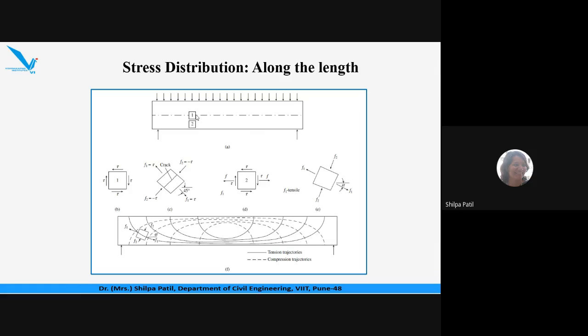So according to that, at the neutral axis, the bending stresses are 0, whereas the shear stresses are maximum. So if I want to show the stresses acting on this element number 1, it is subjected to pure shear because the bending stresses are 0 at the neutral axis and shear stresses are maximum. So along with this particular element 1, if I draw a free body diagram of this element, I can show here the shear stresses acting along this particular element.